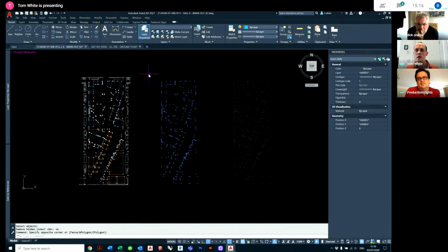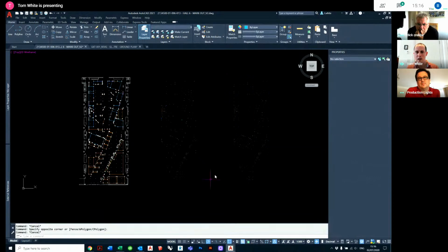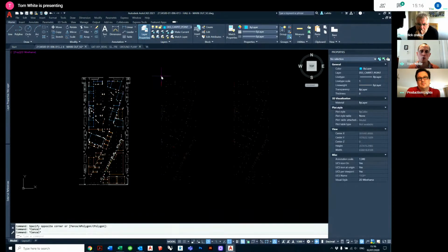So that was two ways of changing the points from a Z value of something other than 0 to 0. On the right-hand side one, we overwrote it in the geometry, and on the left-hand side one, we used a command called flatten.